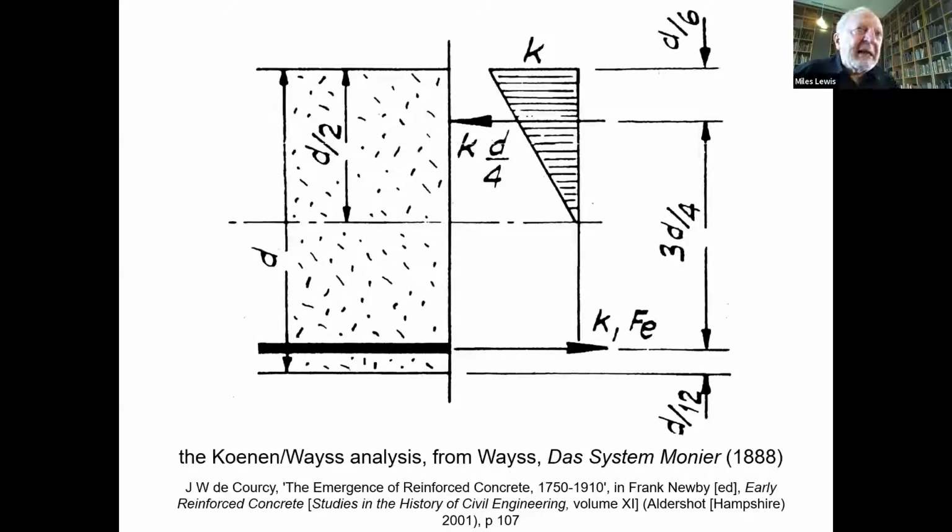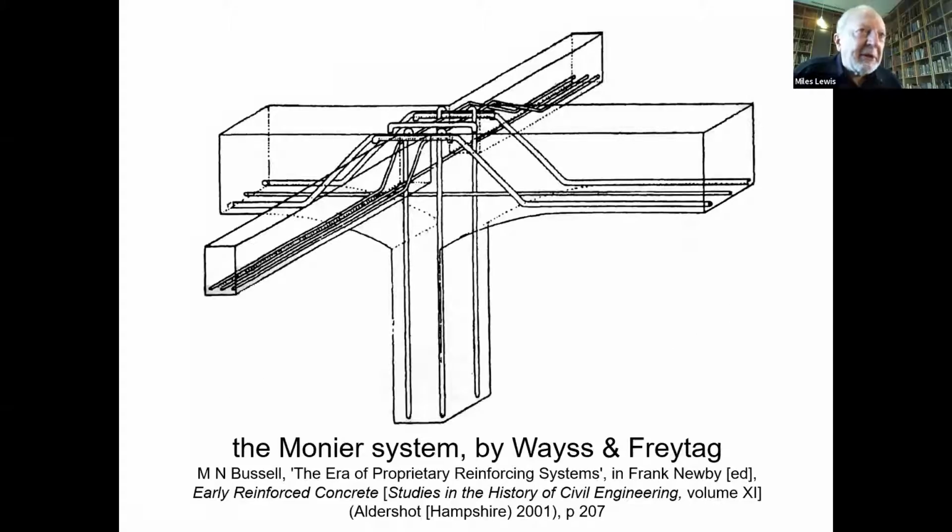And in particular, they learned how to analyze these stresses. So this is approaching really the way you'd analyze a slab or beam today, with the moment of inertia for the concrete and compression at the top, but at the bottom, of course, only the steel is taking the tension load, setting a moment between the two. And the Monnier system now is more and more scientific because the rods are being placed at the bottom where the tension is, then jacked up at the top over the points of support where the negative bending moment occurs. More and more like modern reinforced concrete.